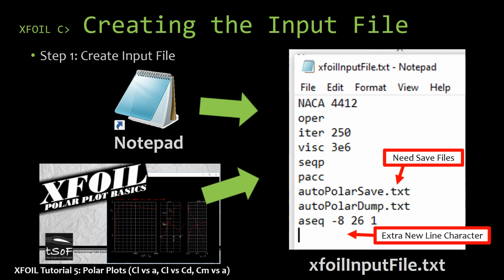When you're done typing up this input file with your list of commands that you want Xfoil to do, go ahead and save this as a TXT file in the same location that you have your Xfoil application. I'm going to go ahead and name mine Xfoil inputfile.txt.